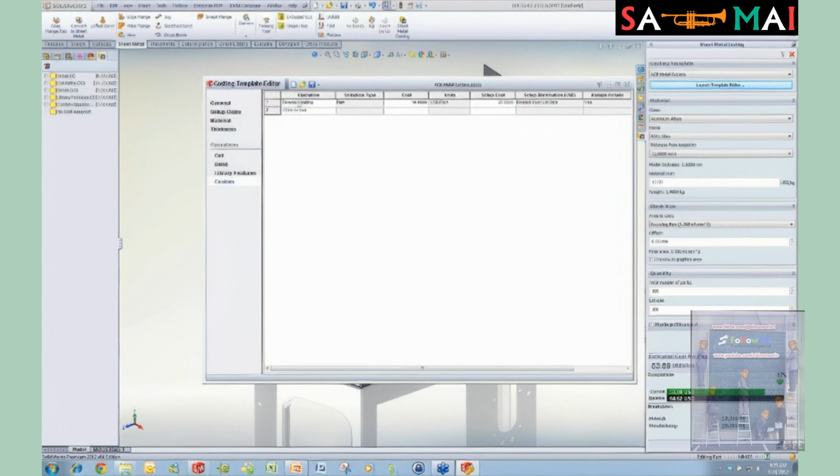And for custom, we can say, well, here's our powder coat. Maybe I want a custom to be dipped. For selection type, let's do the whole part. Cost is going to be $5. And our setup cost, we don't really have to do much setup, so let's say it's $10. And let's say that's divided over the entire lot. Always include no.